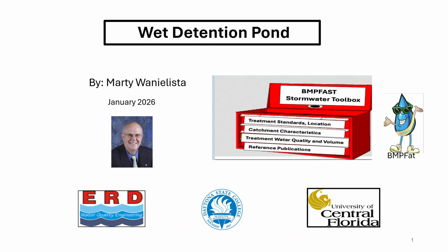This crucial finding demonstrated a clear relationship between the residency time of water in the pond and its ability to reduce pollutant loads. Further documentation solidified their value, particularly in controlling total nitrogen and total phosphorus, directly linking their effectiveness to the presence of a permanent pool of water within the pond structure.